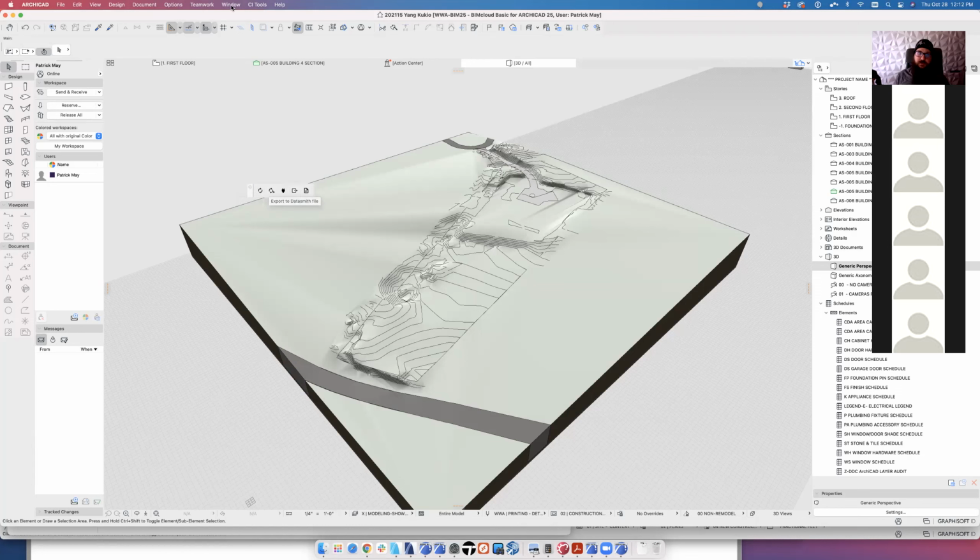We just have to go to Window, Palettes, and Datasmith in order to get to that export function. And just know that it's not an FBX any longer. It is going to be this Datasmith sort of proprietary thing.